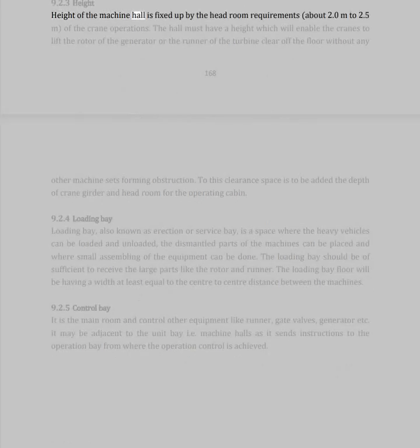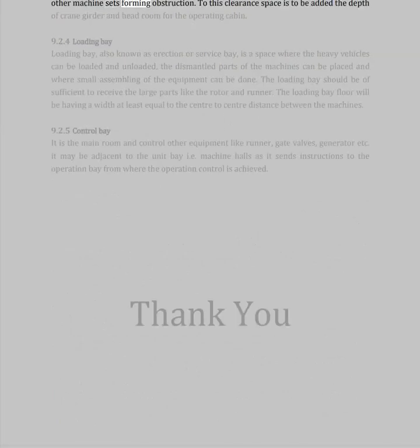9.2.3 Height of the machine hall is fixed up by the headroom requirements, about 2.0 m to 2.5 m, of the crane operations. The hall must have a height which will enable the cranes to lift the rotor of the generator or the runner of the turbine clear off the floor without any other machine sets forming obstruction. To this clearance space is to be added the depth of crane girder and headroom for the operating cabin.